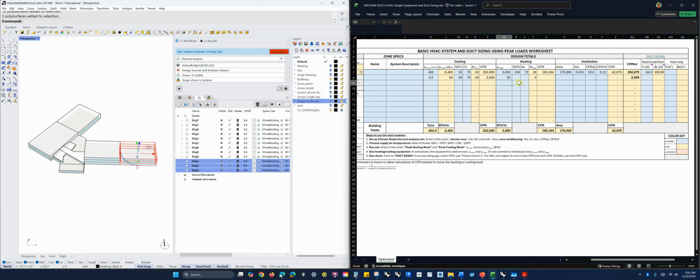And then these are our, so we could do the same thing, and we could get it for an individual apartment. Of course, we do the same thing here for the ventilation. We could get an individual duct sizing if we wanted to duct it, or if we're just doing fresh air, that might be another way of doing it. So then we could just use this portion. So my point is that we can then pull out parts of the project and use this spreadsheet to size individual portions, and then pull it together into a complete design.